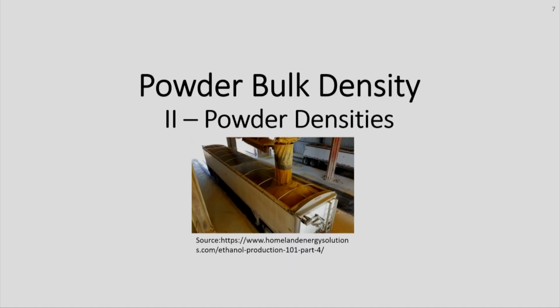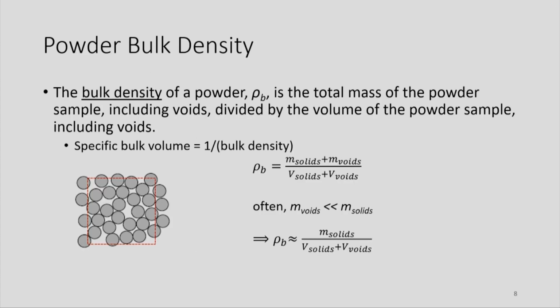Okay, you all gave good replies, right? We characterize lots of different densities. One common density that we calculate is the bulk density. For any powder, bulk density includes all the void space, all the intergranular void space. So if you have powders, you take the void space and include that in the overall volume calculation.